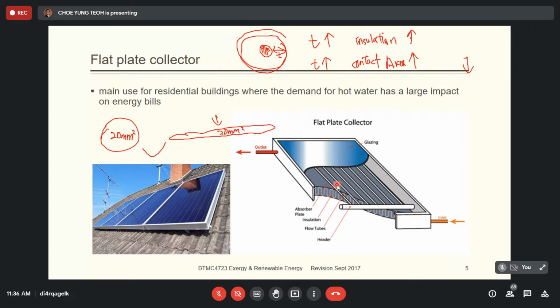The reason to use water is we can get it everywhere and, as we can say, it's very, very cheap. We can get it easily and it's very cheap. And then water has a very high heat capacity and very low viscosity. Very high heat capacity means that it can absorb a lot of heat. If you want to increase the temperature of the water by 1 degree Celsius, you need to supply a lot of energy, so you don't need to flow too much fluid inside the pipe, but you can still absorb the maximum of the energy.